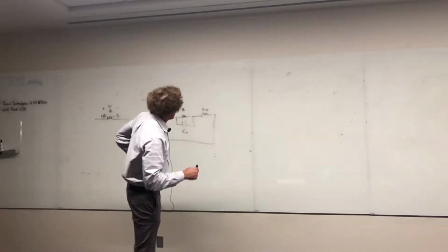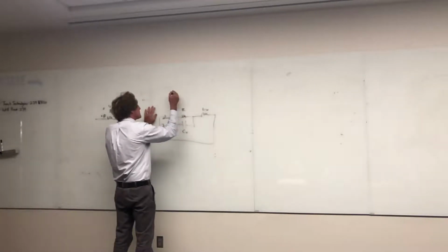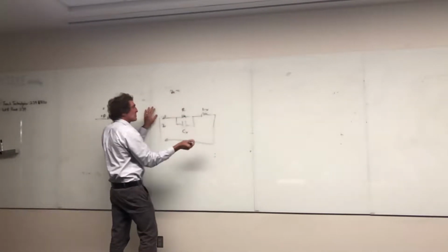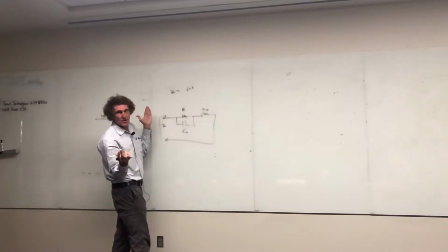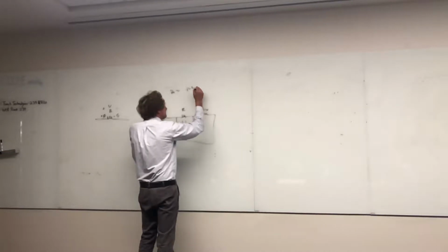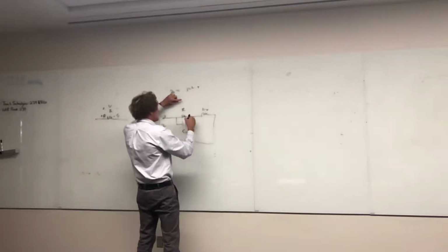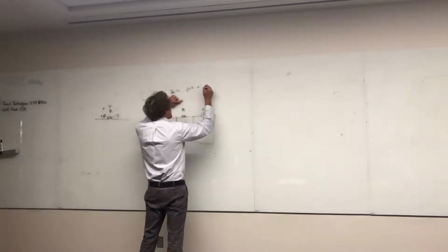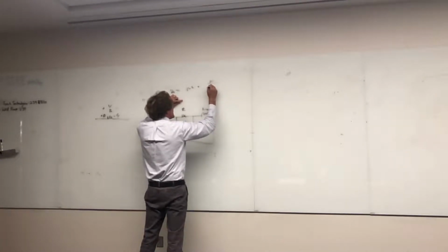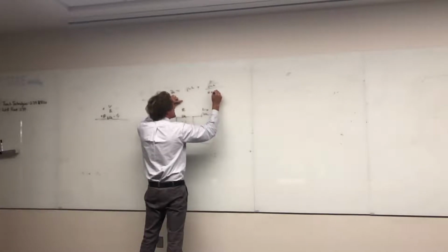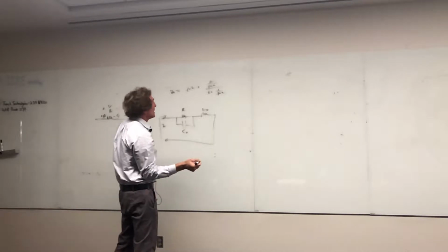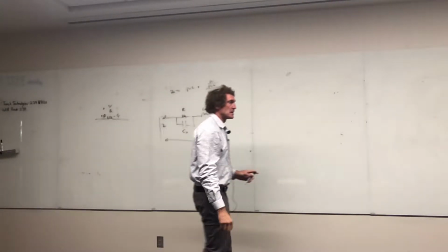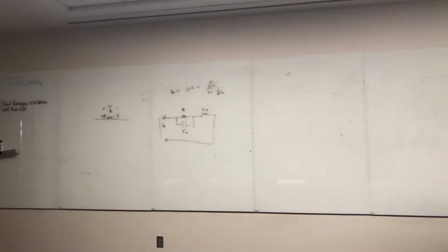So when you look at this input impedance right here, what is Zn? It's equal to j omega L, or sL if you want to use the s domain. And then it's going to be plus, and really it's going to be these two. So it's going to be R times, it's really R over j omega C over R plus 1 over j omega C. And if you multiply top and bottom by j omega C, which I'm about to, you get this.